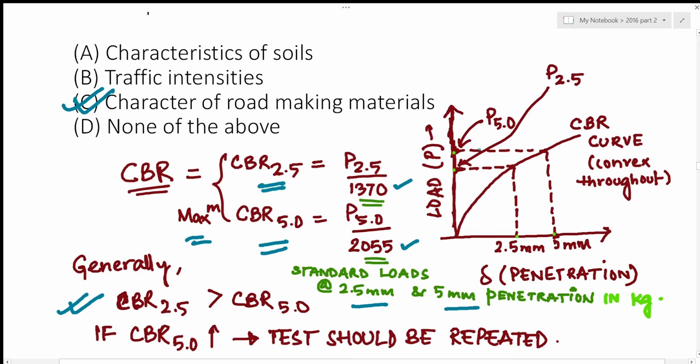And also this is the graph between the load and penetration. This is the CBR graph. This should be convex throughout. If you have any concavity in the curve, you should repeat the test again.